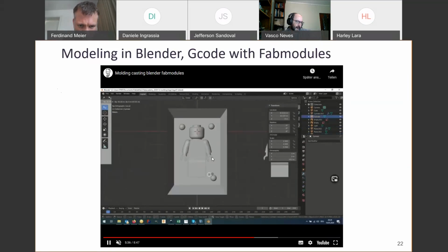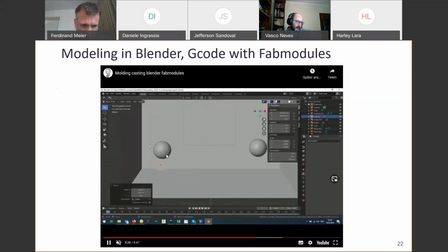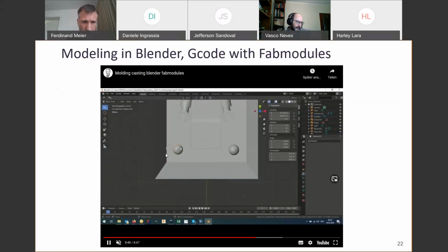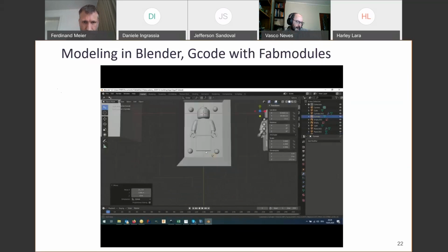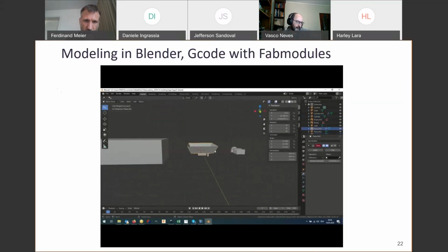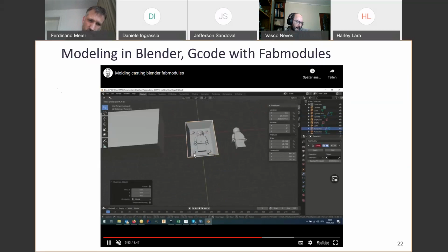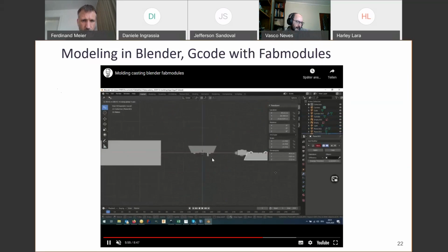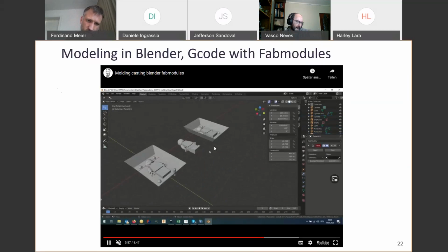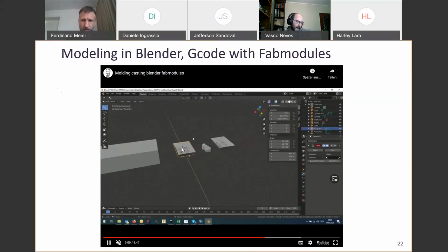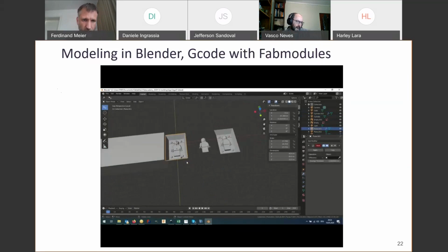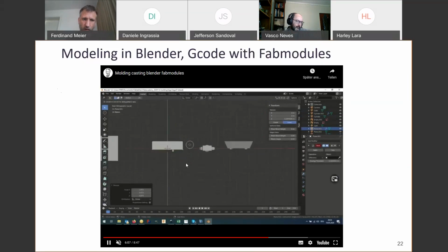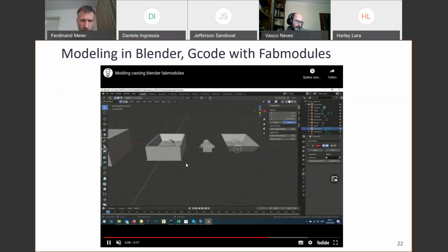And you can see me going around with my little mill just for checking if it's in the right position. And yeah, so I have to move it forth and back and check, and then I cut the spheres on one side and I add them on the other side. But yeah, as I said, the better solution is to have the two mold halves register just by having a contour that is going up on one side and going down on the other.